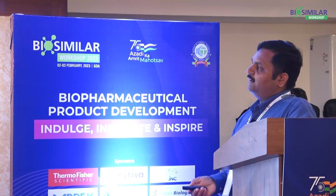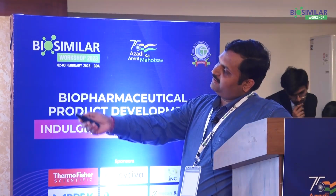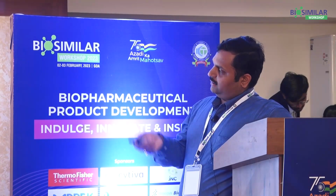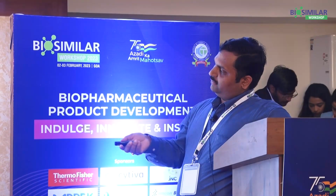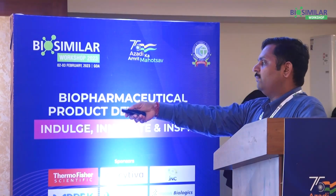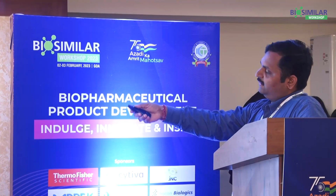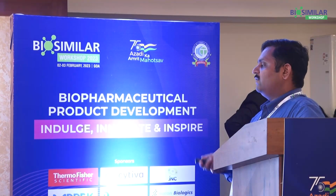Just to explain in a pictorial diagram, here on the left-hand side, there are two columns connected with each other. The first column is loaded, and once it crosses the maximum loading capacity, the breakthrough from the first column is collected on the second. Moving to the right-hand side top figure, the breakthrough from the first was captured on the second column, and the first column can be disconnected. This disconnected column can be taken for washes, elution, and regeneration for loading again.